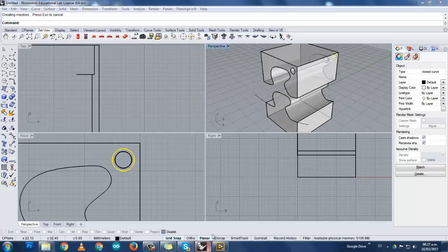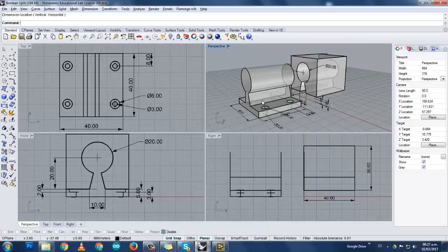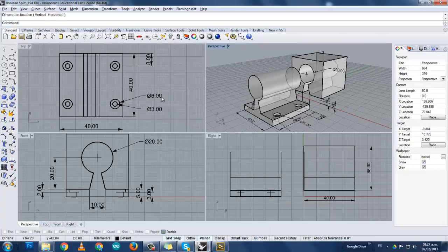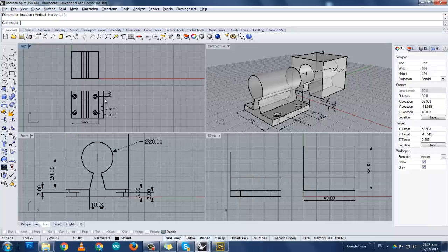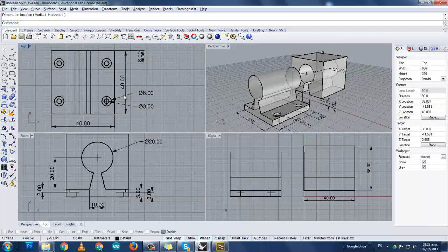In your case, you are going to develop the following isometric, and this is your isometric figure. On the top view you have all the measurements for the two objects that you have to create. Remember that you start from one object. You start from this cube, which is 40 by 40. Okay, the cube is exactly 40 by 40, and then you draw this line right over here.